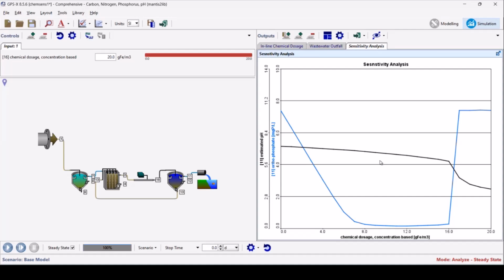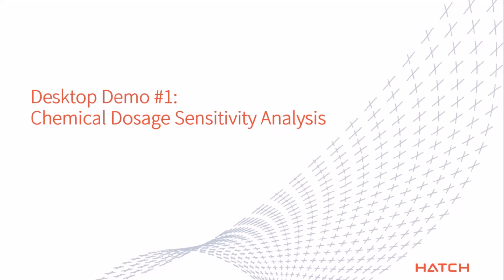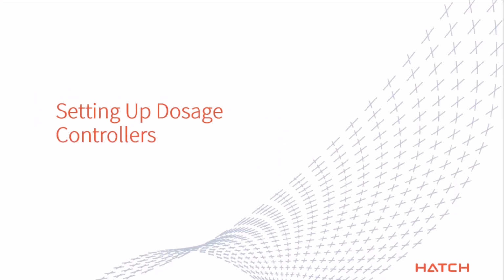So that's doing it with the visualized sensitivity analysis method, and Jacob's going to come along later on and show us a more advanced, more sophisticated version of this with 2 dosage points. But before we get there, I'm going to go back to my slides again, because I want to wind up this part of the talk with how to set up the chemical dosage controllers, automatic controllers that can change things in order to hit certain set points, and also using the operating cost model. So understanding how to calculate how much a chemical is going to cost, and if you have dynamics, how it's going to respond to the dynamics over time.